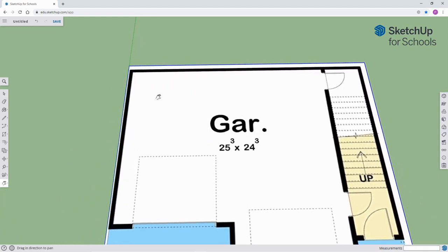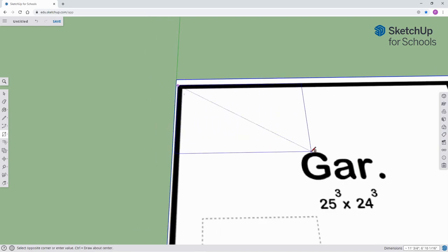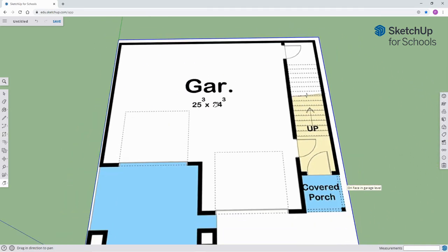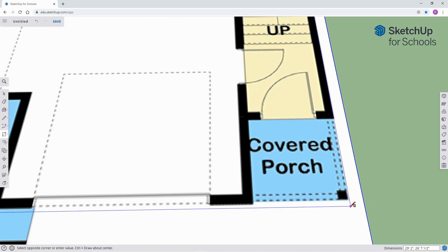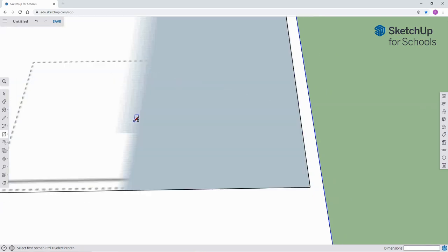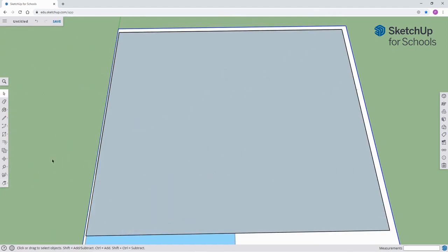Pan and orbit. For a nice position, we will now hit hotkey R, and we will outline the perimeter of the ground level of our modern house. I'm taking my time to align things correctly. Notice it turns gray. Don't let that scare you. It's normal. It means you've done things correctly.